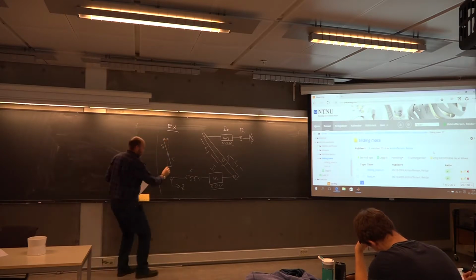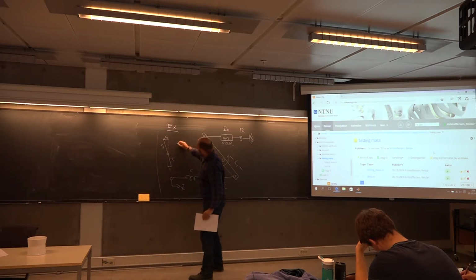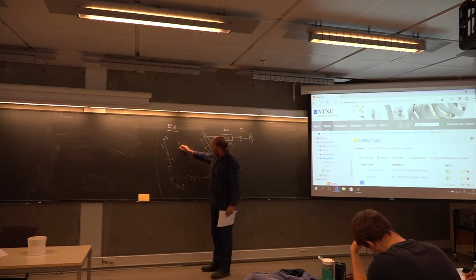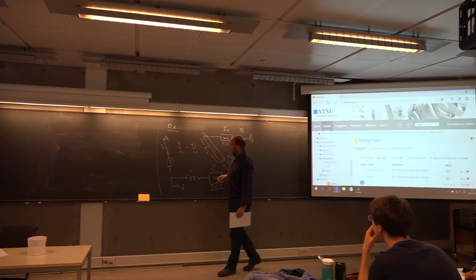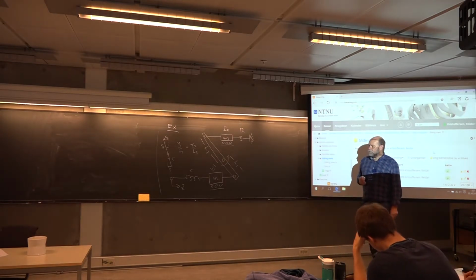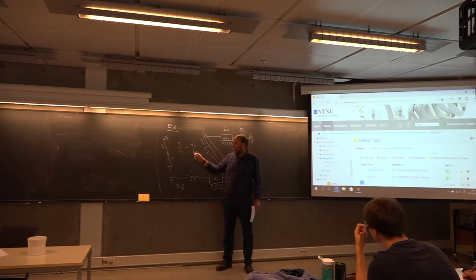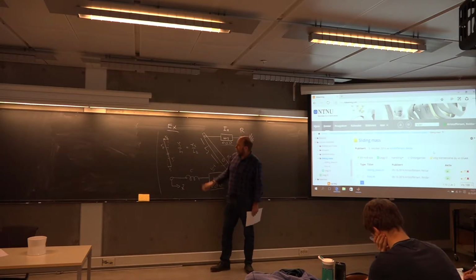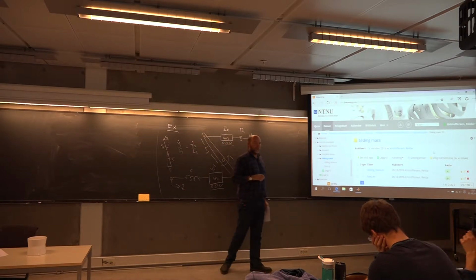If I now call this one y1 and this one y2, then you will have the following coupling between them: y1 divided by L1, this angle equals this angle, y2 by L2. That must be sort of given. This also means if you are looking at velocities, just take the time derivative of this equation. What do you get? The velocity is coupled with the velocity. Yes, clearly this is a transformer.